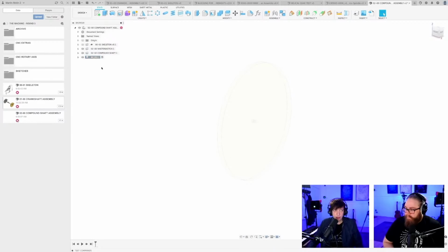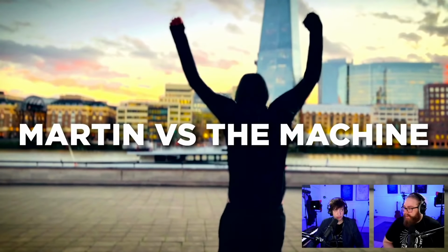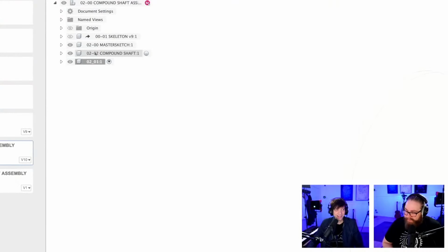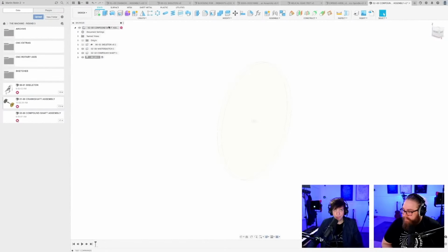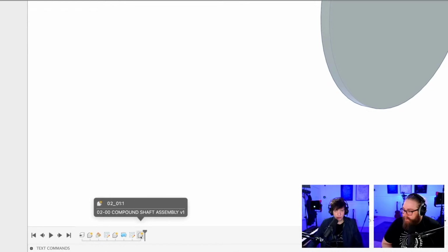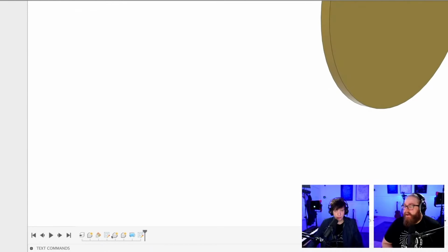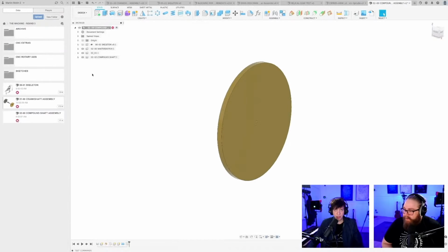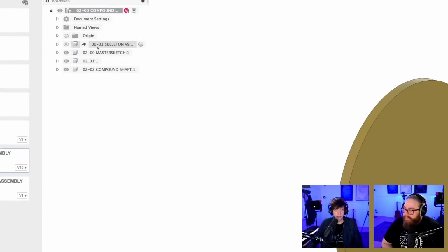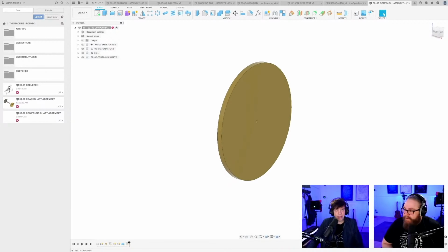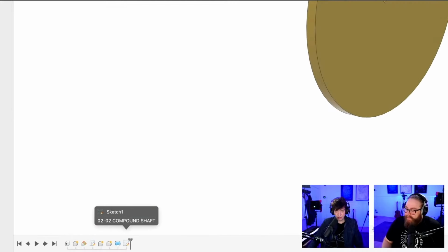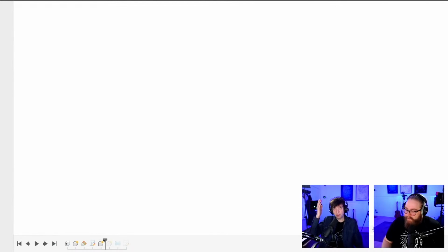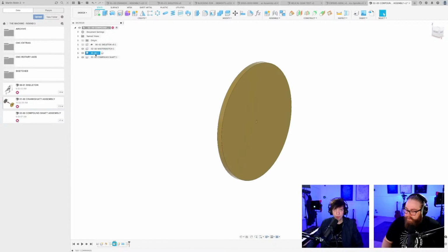But as you can see, it's not at the correct place in the list. So what you have to do then is go down to your timeline and drag that component before the other one in time. That makes sense. And look here, they are in the correct position. Boom. You could also move the timeline back like this, and create a component at that point in time, and it will end up at the correct place in the position.